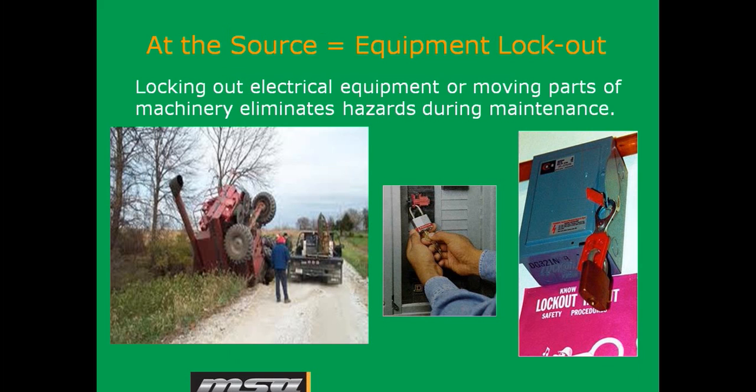What about equipment lockout, tagout? A problem that we come across is with farm machinery. A lot of times the ignition key is the same, one key fits all, for a lot of pieces of equipment. And we may have a technician working in the engine compartment on a combine, maybe changing a fan belt, and another technician jumps in to start the combine to move it. Well, it's not going to be a good day for either of those people involved in that accident.